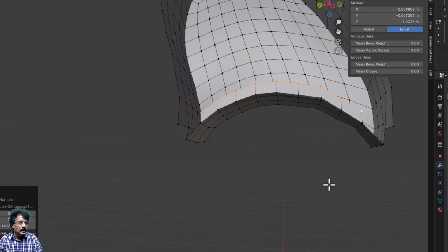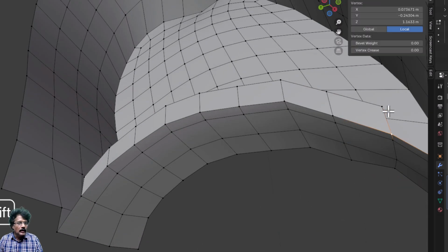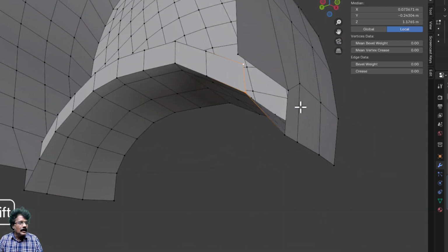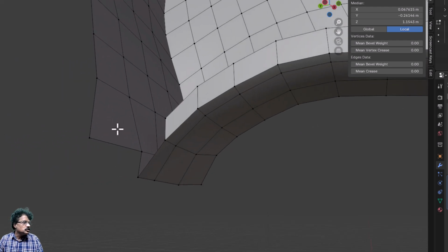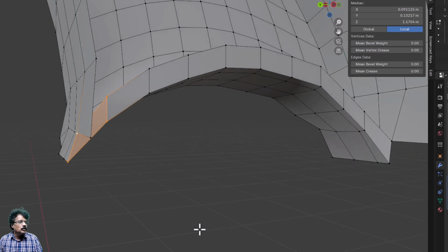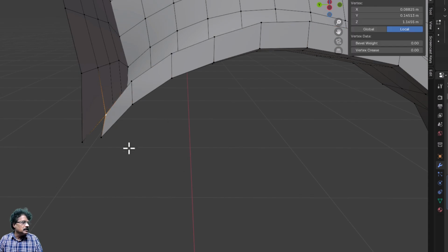After I create this extrusion, I now have to select 1, 2, these two faces, then Shift-click and select 3 and 4. I will select these 4 and press F and close this. Similarly here, 1, 2, 3 and 4, and I am going to press F and close this. Then I am going to select this entire loop. I will press Alt and click from this end.